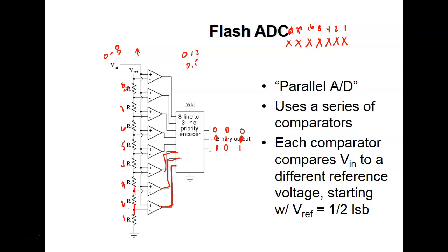So these flash converters are extremely fast. But the problem is they take a lot of hardware. They're going to consume a lot of power, right? Every one of these circuits that you put in there is going to require current to run that circuit. So there's got to be a better way, right? But these are fast. So if I needed instantaneous conversion, then this is the guy you would have to get to. Is this what your meter uses?